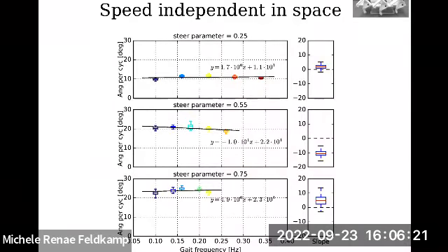One interesting thing we're seeing is if we look at how much response we get for our turning behavior, so how fast are we turning for different speeds, it looks like the response is independent of speed, which is what you expect from the geometric mechanics equation that had no velocity, no time dimensions in it, right?